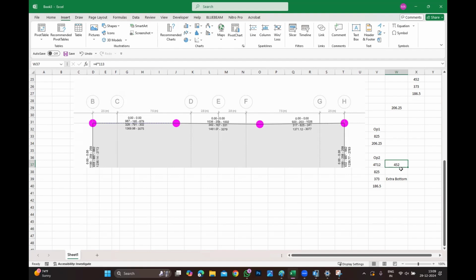In beams, quite often when there is a huge beam depth, we go for a second layer, third layer, fourth layer when the beam length is more. If it is 10 meters, 15 meters, 20 meters, then you demand huge reinforcement. It often happens in design. You'll have 4 layers, 5 layers. Then obviously your effective depth is going to get reduced.